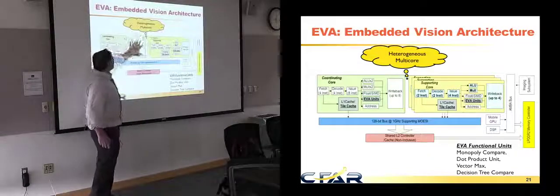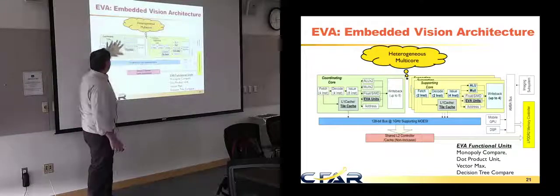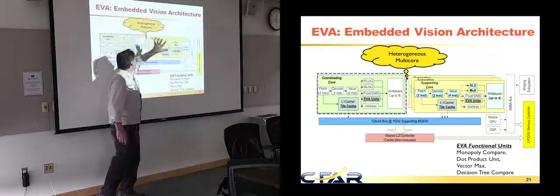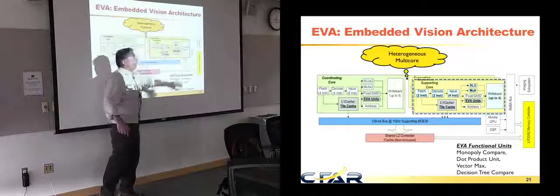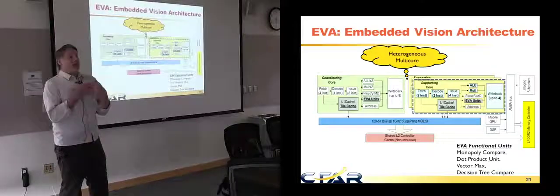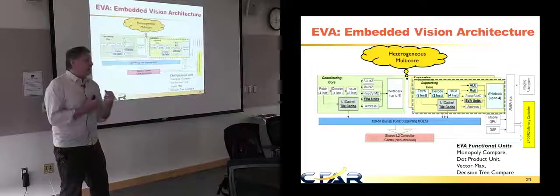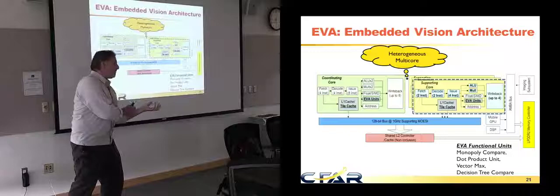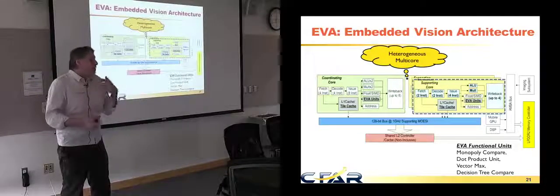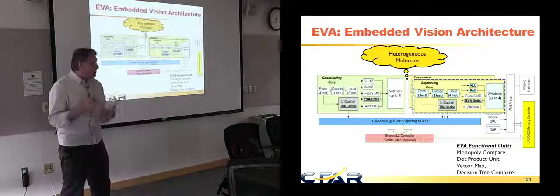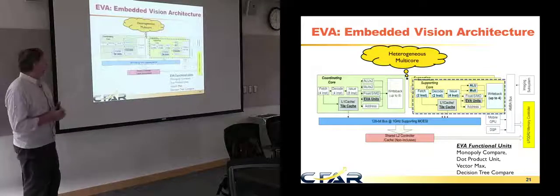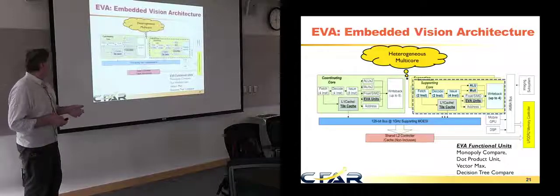For one thing, it's a heterogeneous multi-core. So it's composed of a couple big powerful cores that are serving stuff to a lot of very small cores. In that environment, you can expose a lot of parallelism, and if you can tease out which threads need capable cores versus simple cores, you can do an assignment and you can get more performance per energy, more performance per area, which is also important in the embedded space.